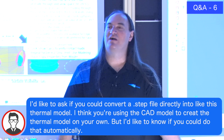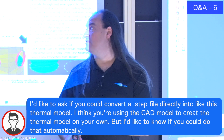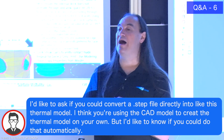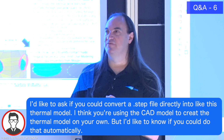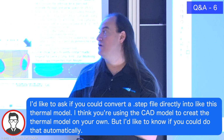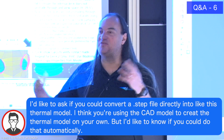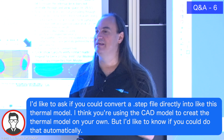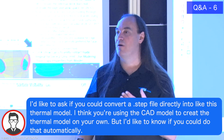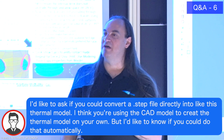We will get to that when we talk about meshers. So there are many meshers on the market. There's SpaceClaim, which has it. There's FEMAP. There's the mesh controllers in Thermal Desktop. But it requires that you define your CAD to be able to be meshed appropriately. And we'll show how, if you don't do that, you can suddenly go from this to 50,000 elements, which just isn't really needed for something that can be done with a few hundred elements. So there are meshers to be able to do that, but sometimes they don't produce the best models for thermal.